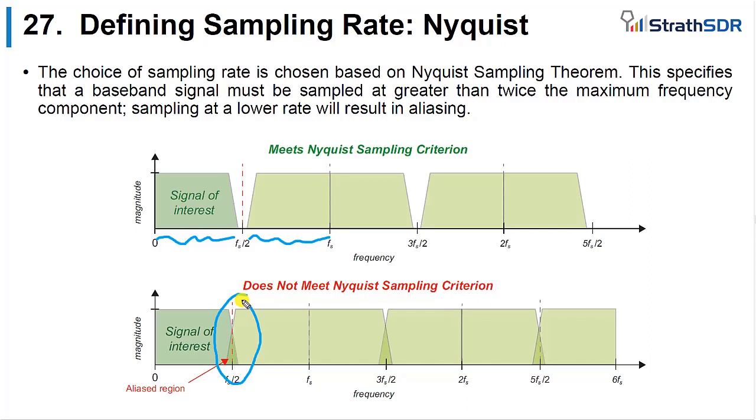There's other things to learn as well about frequency planning. So there are some gotchas with harmonics that will appear from RF and gain stages. So Louise later will take us through some frequency planning and some of the additional things you have to think about to ensure that when you find your signal of interest in the baseband, you minimize any issues with harmonic distortion and some from the nonlinearities in RF and gain stages. So again, a number of new things to understand and consider if you're using RFSoC for the first time.